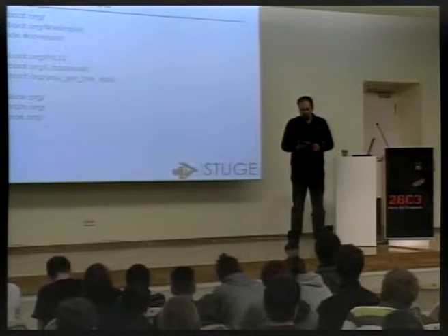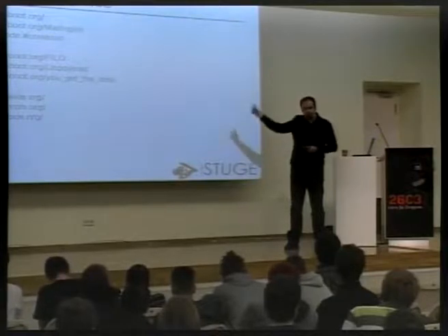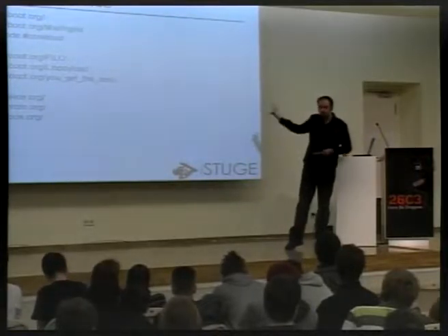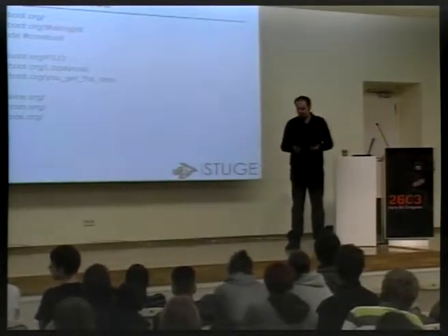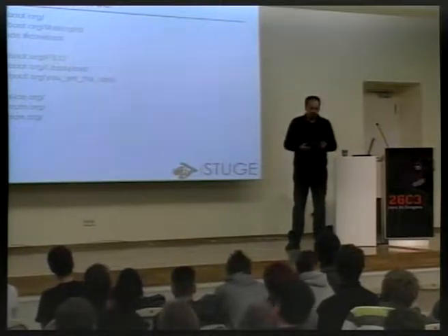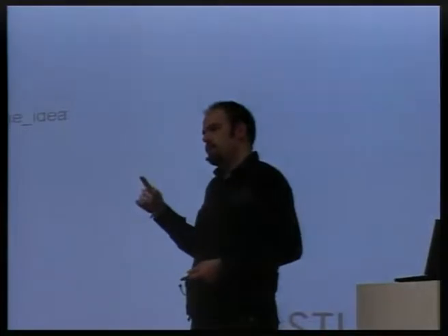So there's a socket for the RAM here, and the RAM has this SPD memory. So maybe you can use that I2C bus to send out debug messages, or maybe you can use the flash chip accesses. If you have a ROM emulator, you can set it up so that if you read from a special sequence of addresses in the flash chip, that actually translates to a debug output write. Okay, the way I see it, then you mean like for your development, you make a patch to see what you're actually doing.